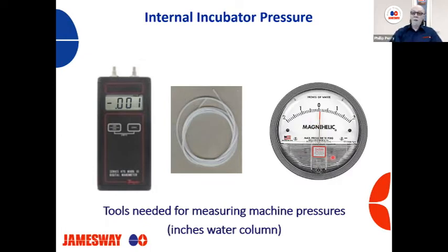So I've gone in and they'll say, well, my Magnehelic says everything's correct, but it's reading the same value that your regular room controller, your electronic controller for the pressure of the room, is reading. So it's always a good measure to have an independent reading of the rooms to make sure that we have the proper pressure in those rooms.